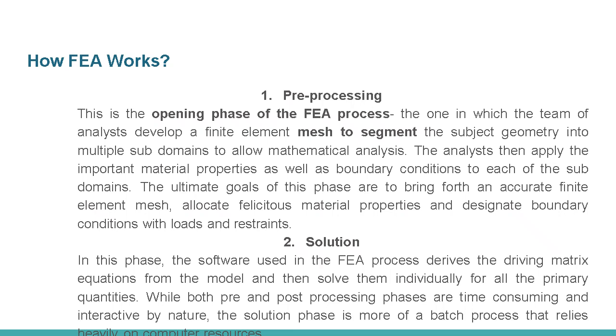So the analyst can apply important material properties as well as boundary conditions to the subdomains. The ultimate goal at this phase is to bring forth an accurate finite element mesh, allocate material properties, and designate boundary conditions. What is the load and the resistance? That is the pre-processing of the finite element analysis.